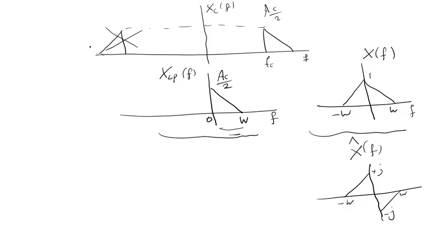I can multiply this one by j. If I multiply by j, what will we have? j multiplied by minus j is 1, 1 plus 1 is 2. On the other side, j multiplied by j is minus 1, with 1 added to minus 1 is 0. So this sideband is removed. But the amplitude for this one is 2. So I can write